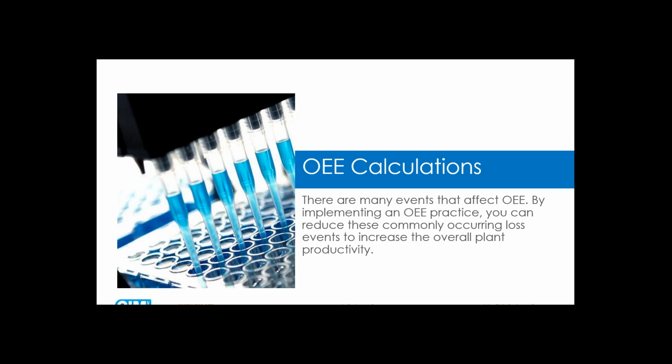But there are many things that can affect your OEE. So we've already talked about speed, we've already talked about short stops, faults, alarms. It is just important that we capture them, but also how we measure them. So if we're looking at a line as a whole, do I measure my OEE for the line as a whole, or do I measure individual OEE metrics for each of the key machines? And again, many different schools of thought here.